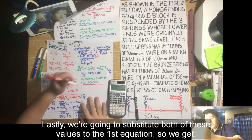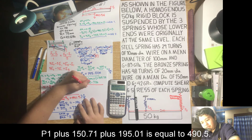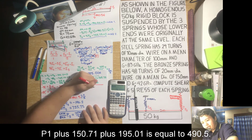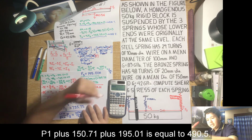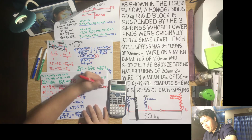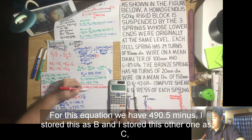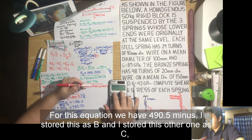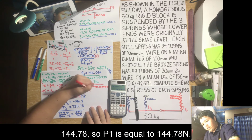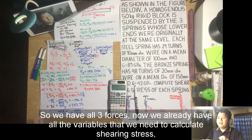Lastly, we're going to substitute both of these values to the first equation. So we get P1 plus 150.71 plus 195.01 is equal to 490.5. So for this equation, we have 490.5 minus, I store this as B and I store this other one as C. 144.78. So P1 is equal to 144.78 newtons. So we have all three forces.